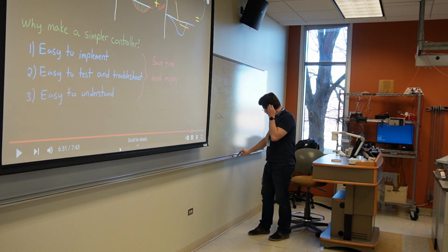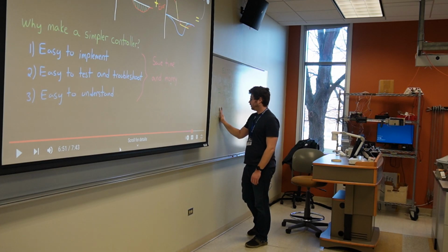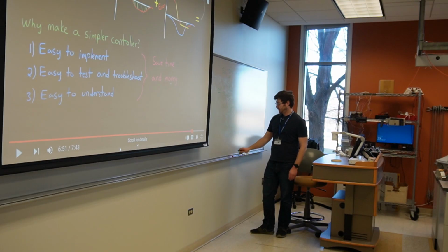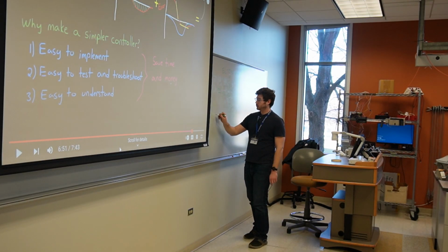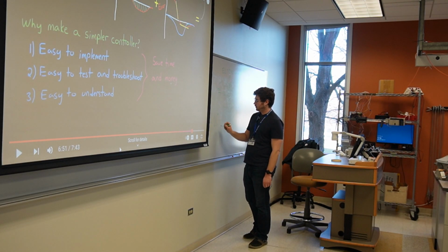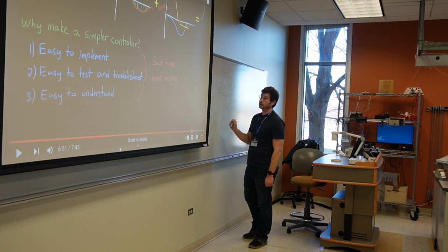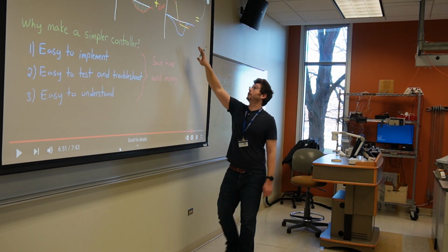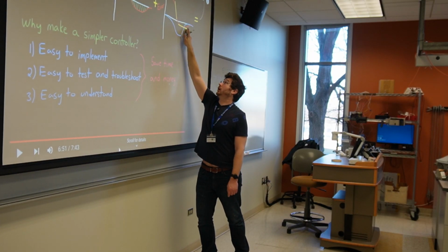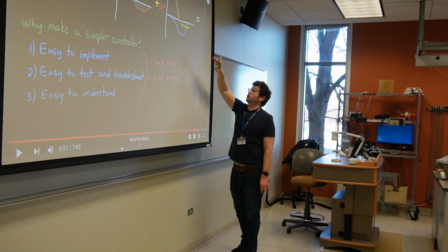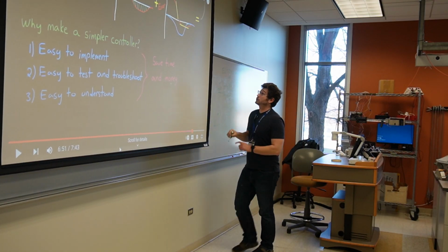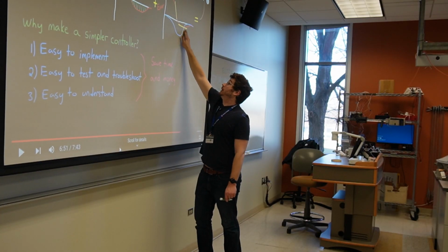The D term, the derivative, is really good for dealing with disturbances. It's the rate of change. So if proportional counters how much is changing, the derivative counters the rate of how much it's changing, the change of the change. That's what we're talking about over here, the slope of the curves at that point. So this term pays attention to the changes at each point in time.